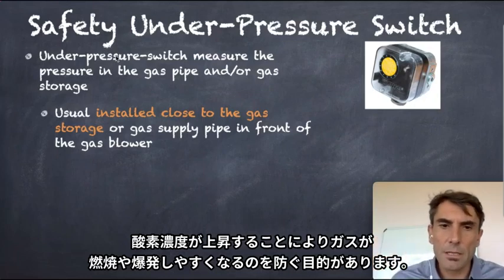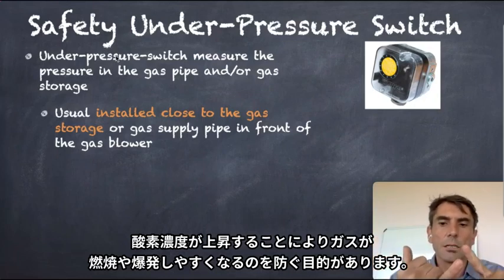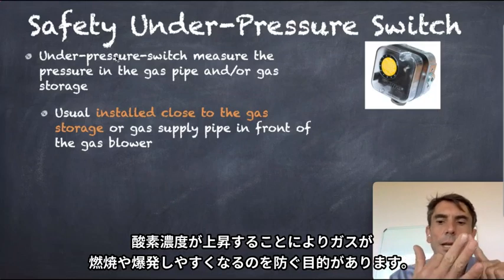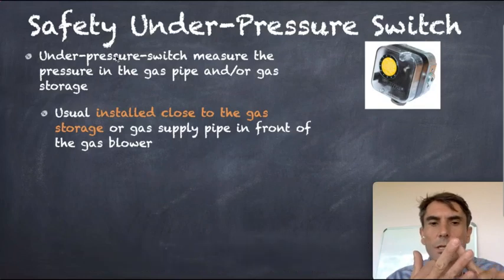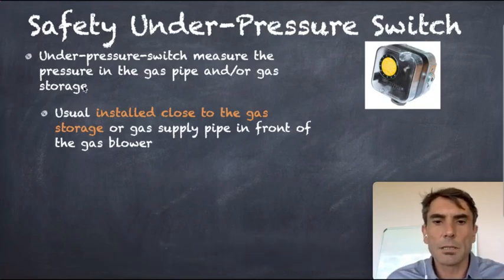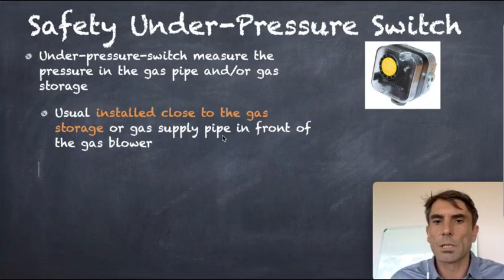To prevent damage to the tanks and the storage, and to prevent sucking oxygen into the gas, there must be an under pressure switch installed.